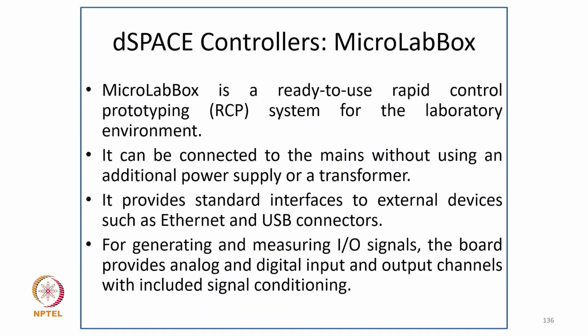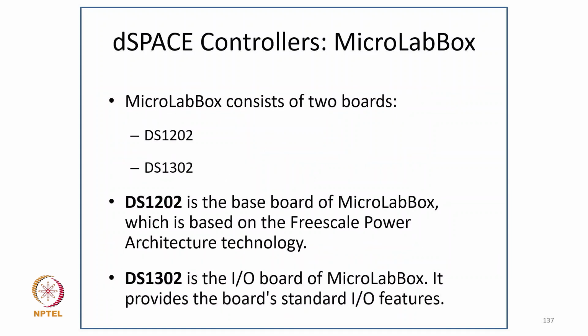So MicroLabBox is the next DSP system by dSPACE controller. MicroLabBox is a ready-to-use rapid control prototyping RCP system for the laboratory environment. It can be connected to the mains without using an additional power supply or a transformer. It provides the standard interface to external devices such as Ethernet or USB connectors for generating or measuring input or output signals. The board provides analog or digital input or output channels with included signal conditioning.